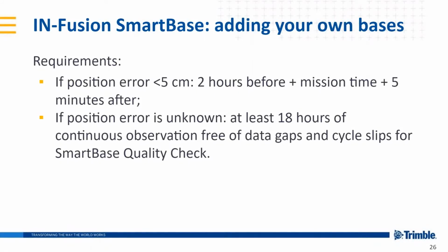This will need some specific requirements. If the position accuracy of the base station is known as less than 5 centimeters, you will need base station data which cover 2 hours before your mission and at least 5 minutes after your mission.